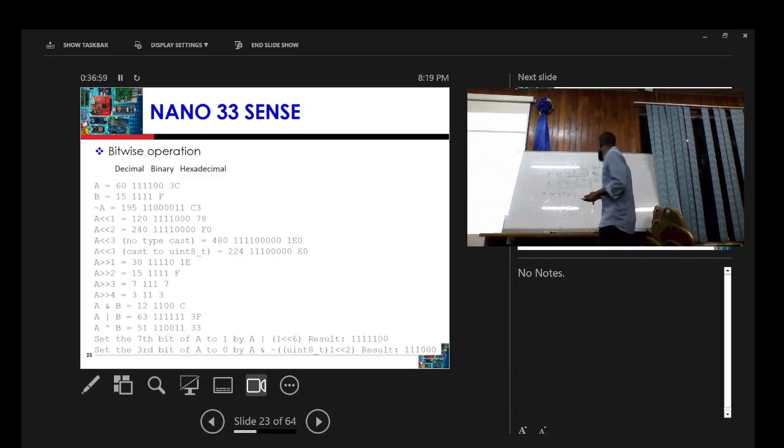And what is the truth table of an AND gate? If I have my input here to be A, my input here to be B, and then my output to be, let's say, Y, I need to draw the truth table, and the truth table looks like this: A, B, and then Y, right? So I need to give it all the possible values of A and B. So A can be 0, B can be 0, right? A can be 0, B can be 1. A can be 1, B can be 0. A can be 1, B can be 1. Easy, right? You guys understand why it is so?